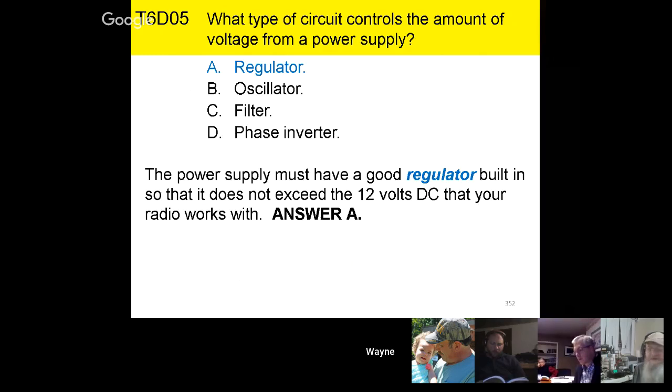A lot of these circuits you'll find will have 16 volts, but the 16 volt transformer takes the 110, 120 volt AC from your house power and steps it down to typically around 16 volts thereabouts, and then of course it will rectify it from an AC to a DC, and you go through some filtering and things like that. But then you have a regulator circuit that actually maintains a consistent voltage from your power supply so you don't tear up your equipment.